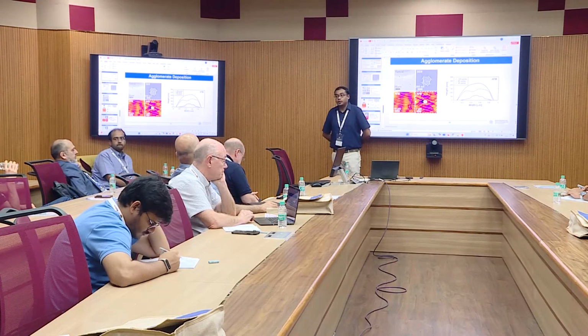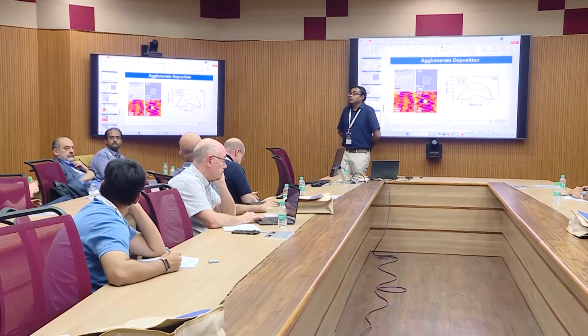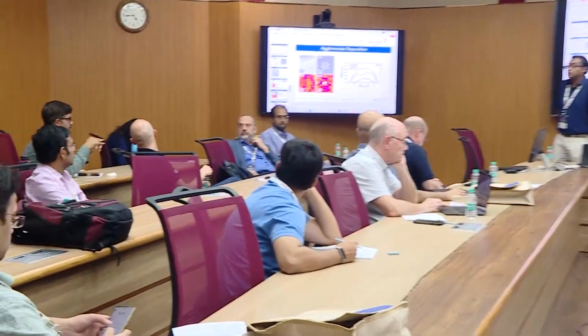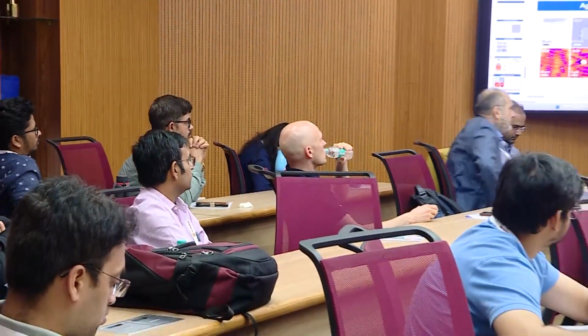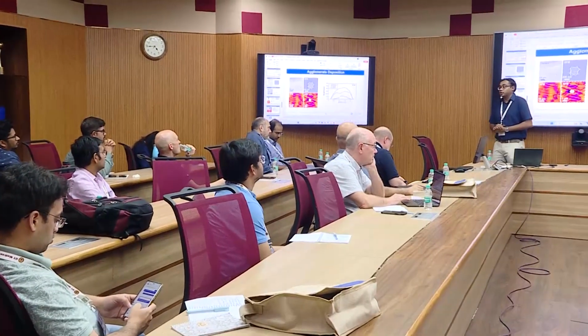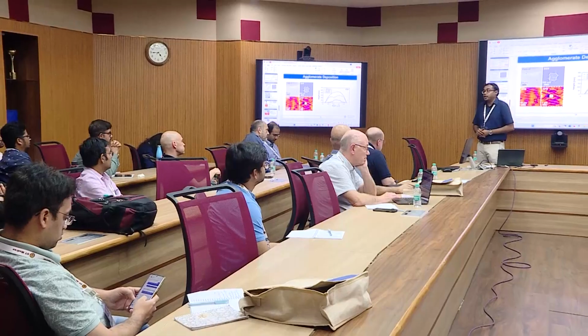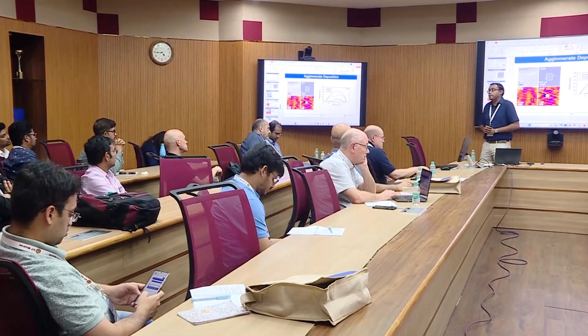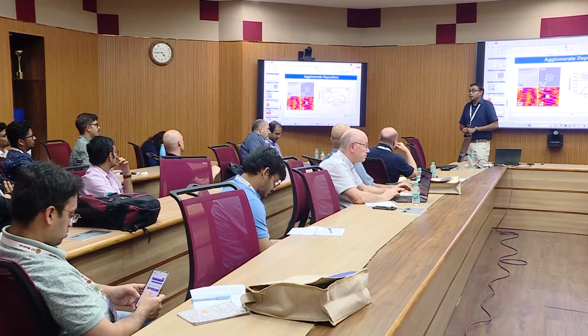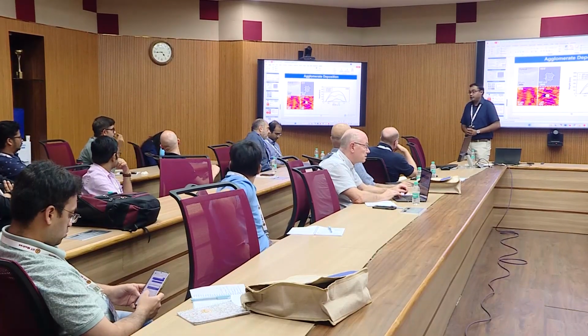Sure. Whether these surfaces are vacuum compatible, meaning if I want to use them in space, is there any degassing issue? The lubricant that we use here, the Krytox, is actually a vacuum grade lubricant. However, given that these are held within the surface by capillary forces, it depends on the level of vacuum. We go down to about 0.1 Pascal, and it is very stable at that pressure. That is high for space applications.